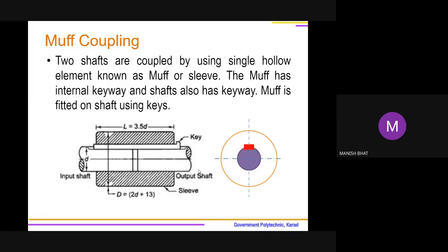And in case of universal joint, we know that the shaft is able to rotate because the wheel is moving up and down depending upon road condition, whereas the gearbox shaft is stationary. So the propeller is continuously moving up and down with the rear axle. So that adjustment is necessary, which is effected by universal joint.